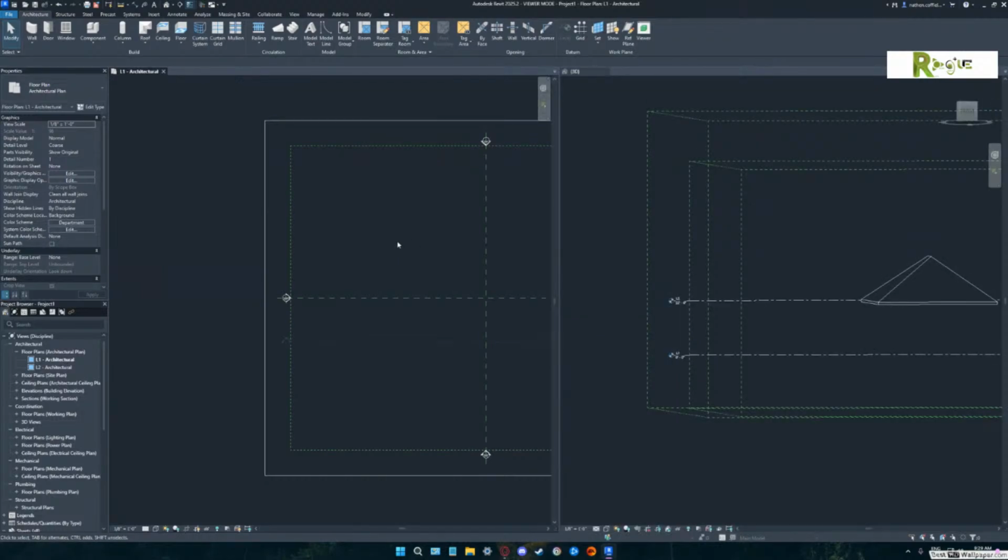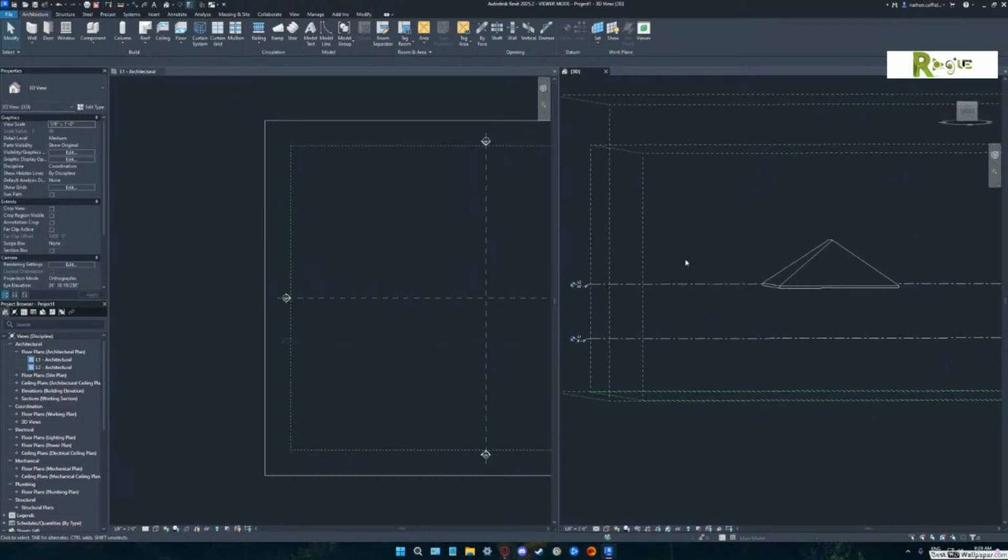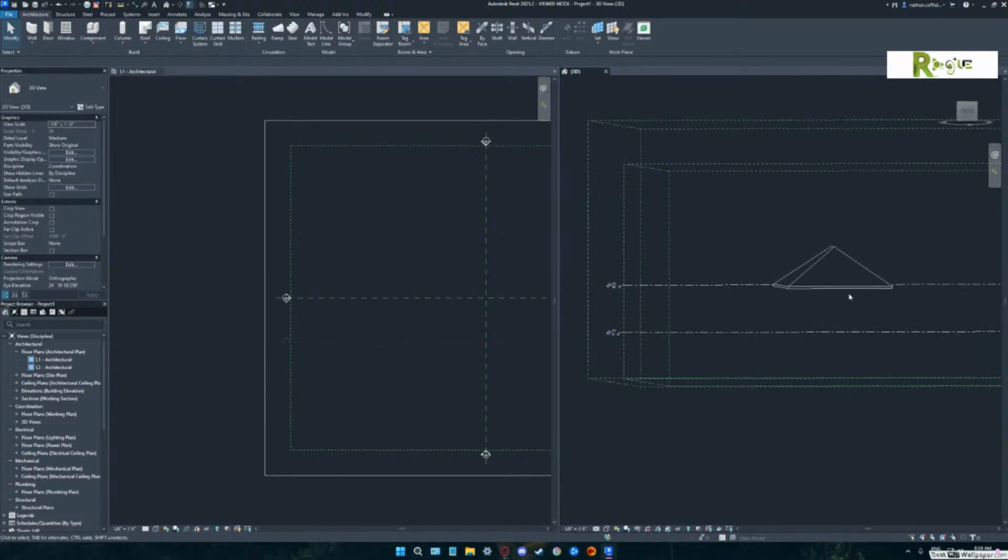And then what you're going to find is Revit is very common. There are shortcut keys that are just 2 letters, and it'll invoke that command. So you can see that when you deleted everything in floor plan mode, you couldn't see the roof, so the roof was left behind. You see how that's done? And you remember we talked about the roller wheel yesterday, and you on your own figured out if you rolled the wheel, you could zoom in and zoom out. And then I showed you if you hold the shift key and click down on the roller wheel, that orbits.